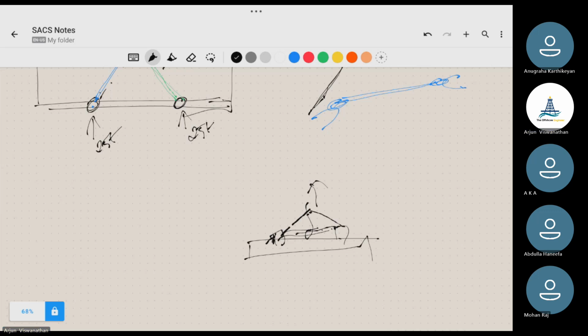Once it is coming upward, the shorter one will show the resistance first. It starts to get loaded and slowly elongates, and when it reaches the length of the other one, only then does the other one also start taking the load.